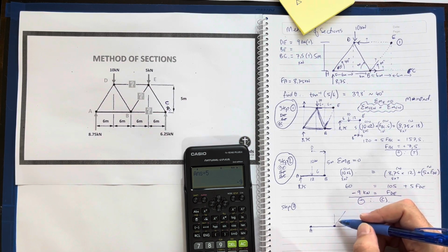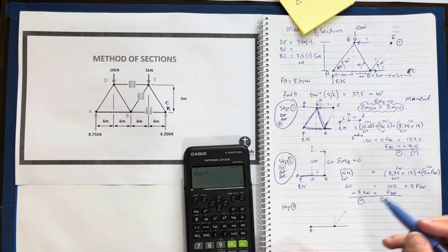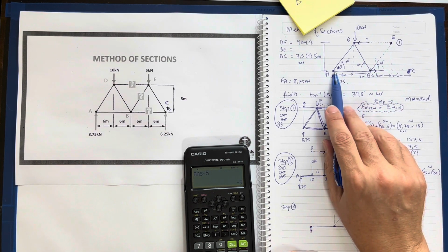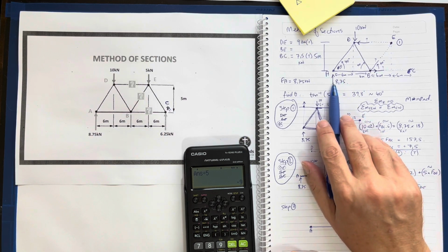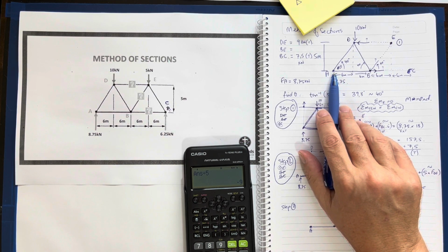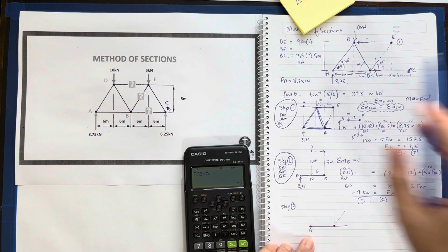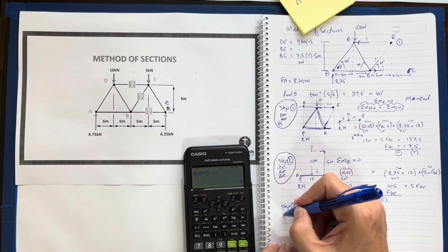And I know that it's going to be that value sine 40 degrees. So straight away, I'm sitting at A. I really can't use this external force because it is right at that joint. Its distance is 0, therefore I don't have a turning moment at that point A for that external force. And so using step 3, I'm going to try and solve for BE.